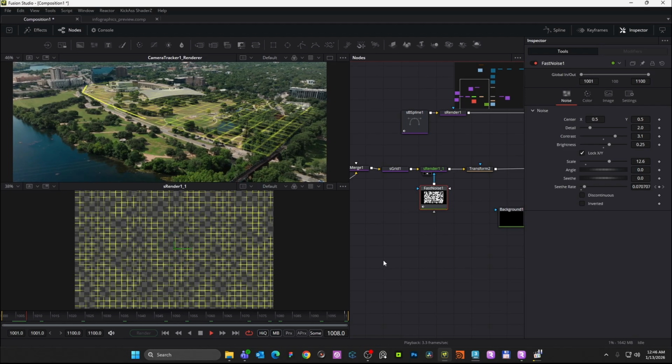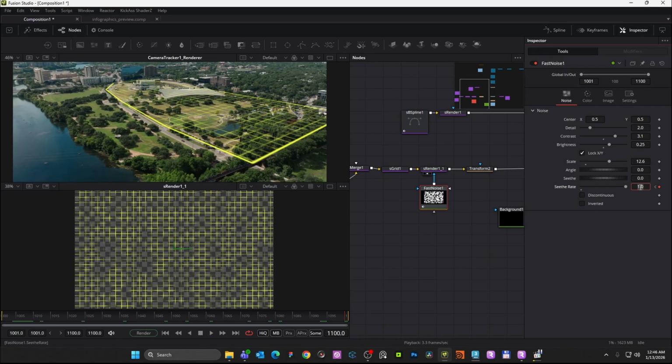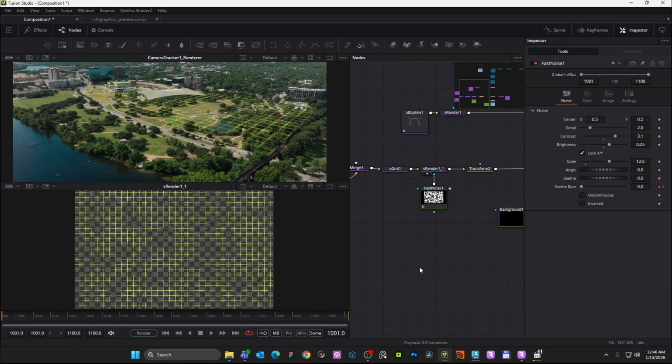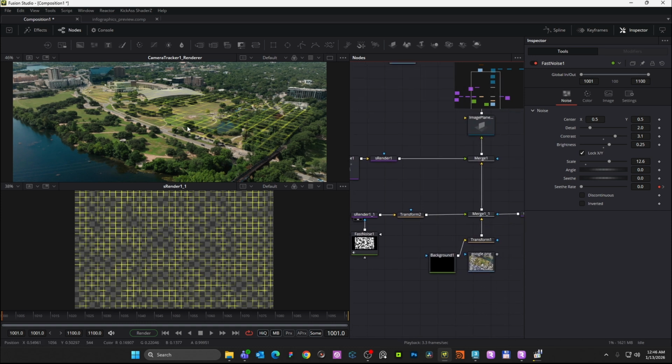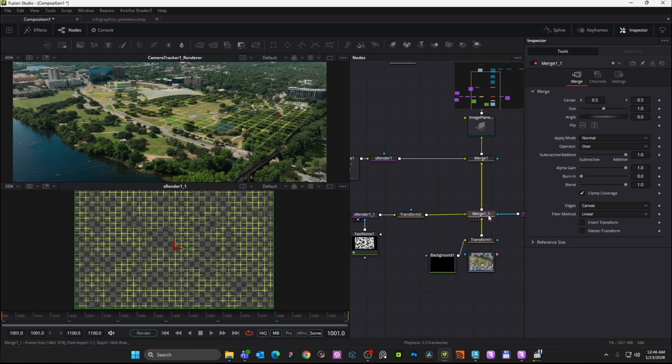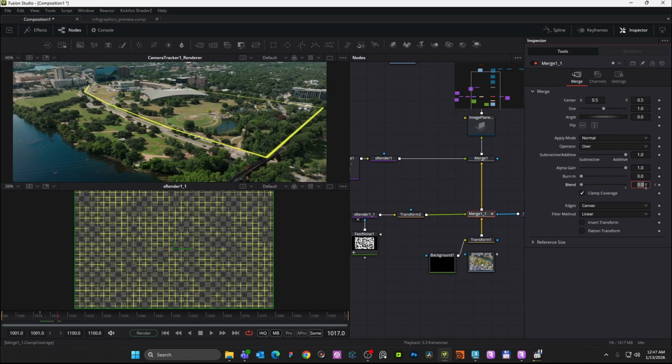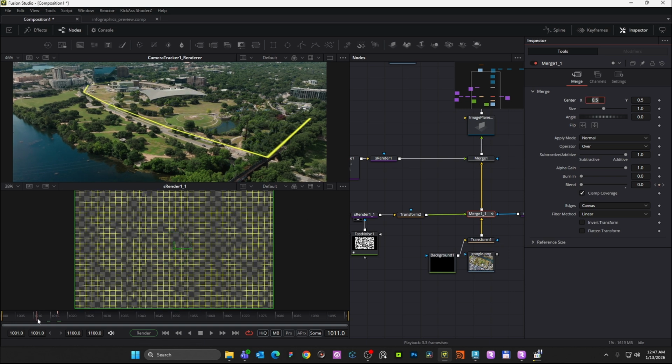That's of course too fast. Let's put 0.2. Right. Yeah, and of course to make it appear not from the frame 0 but later, we can animate this merge blend parameter. In the frame 0 it will be 0 value. A bit later, when our line is building up, we can make another one, and let's say in 6-7 frames I can make it fully visible, like so.